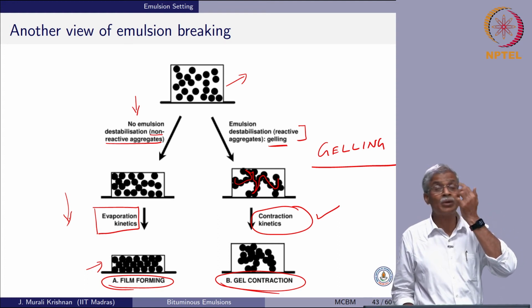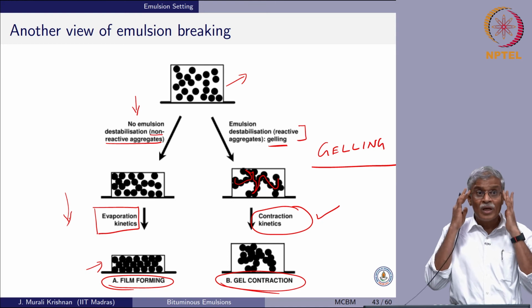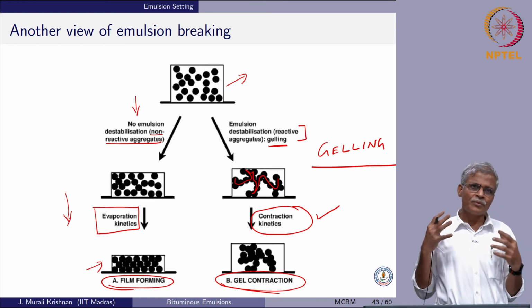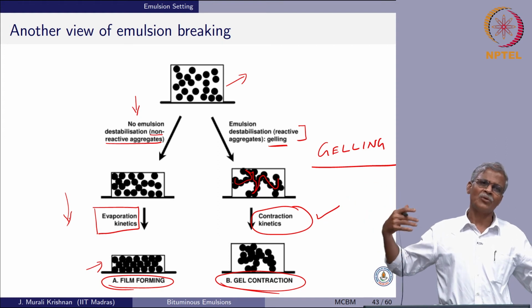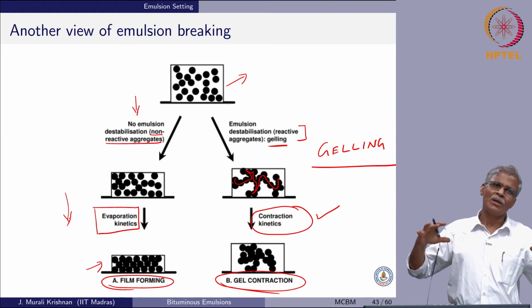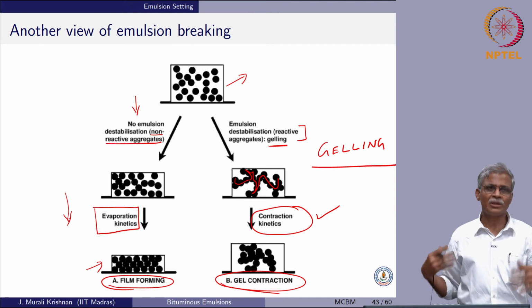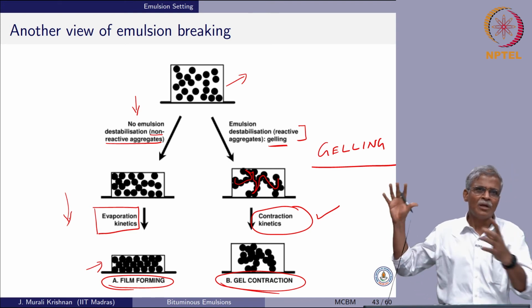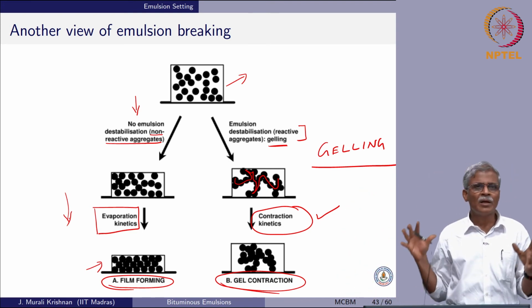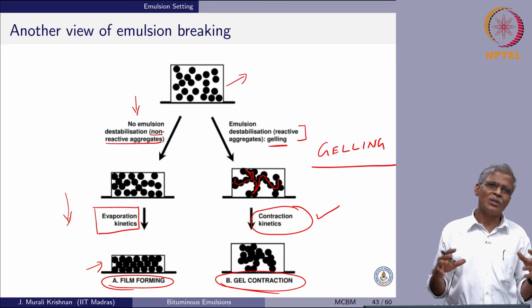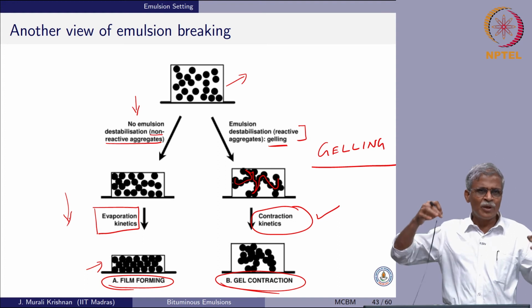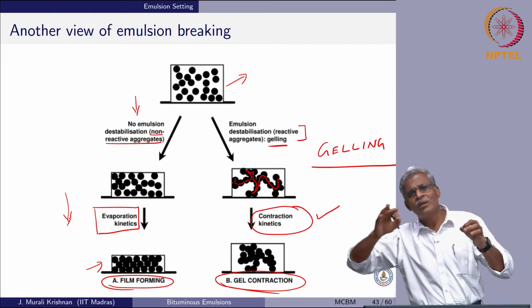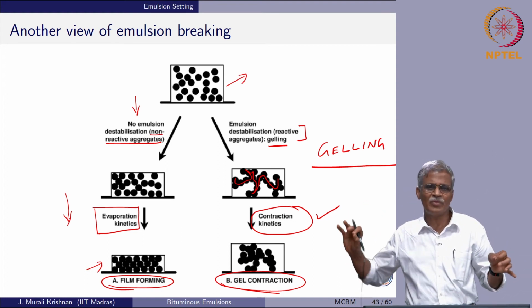So, in all these applications you need to know. Why? Sometimes you can go to the field, get your reclaimed asphalt pavement, pulverize the material, mix it with emulsion and store it like a stock, and the emulsion will start breaking slowly during the construction process.